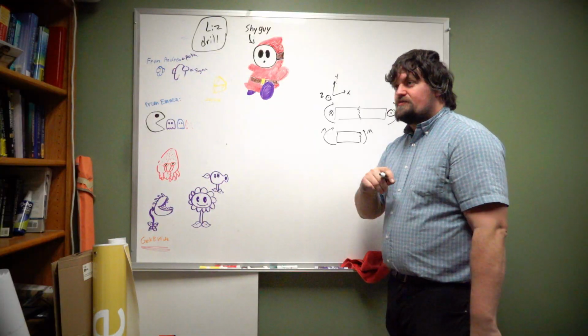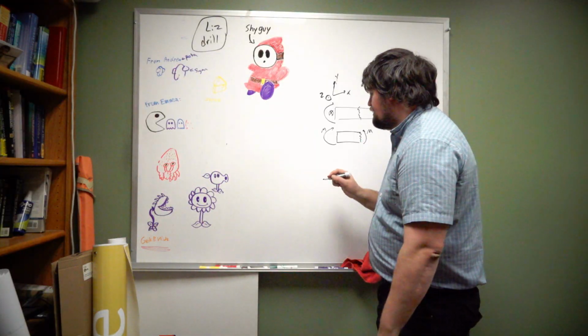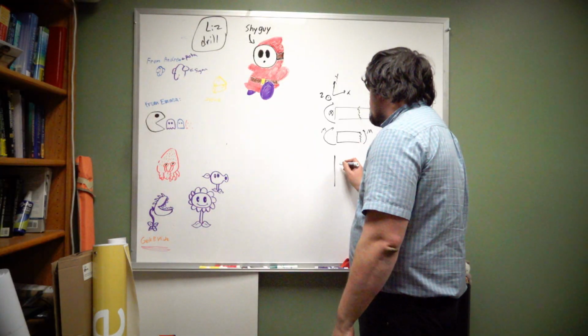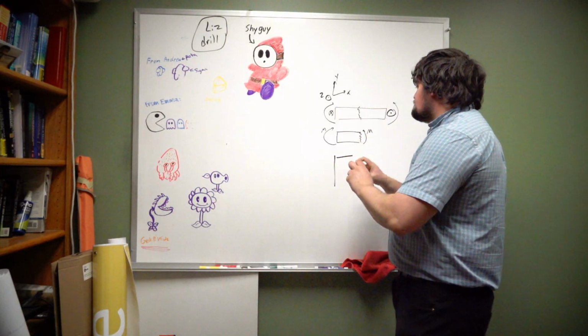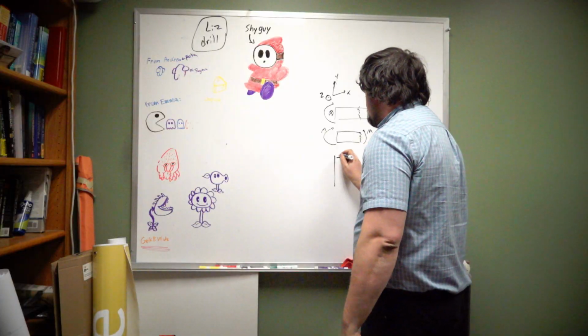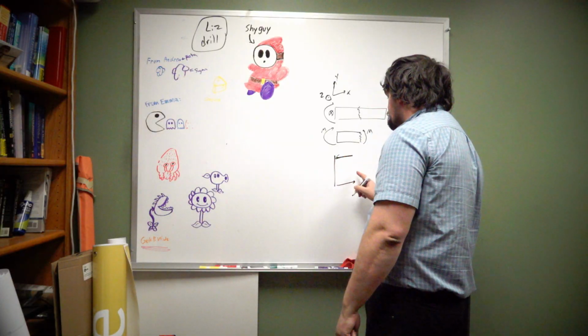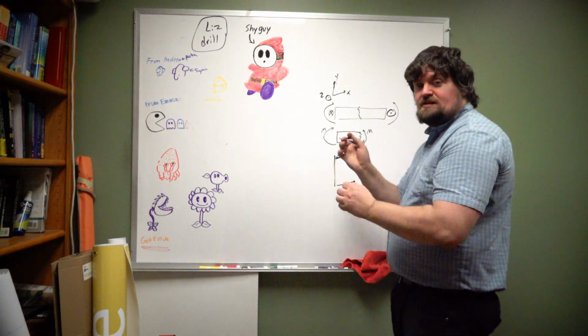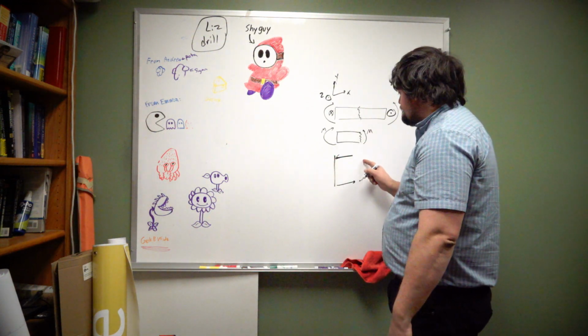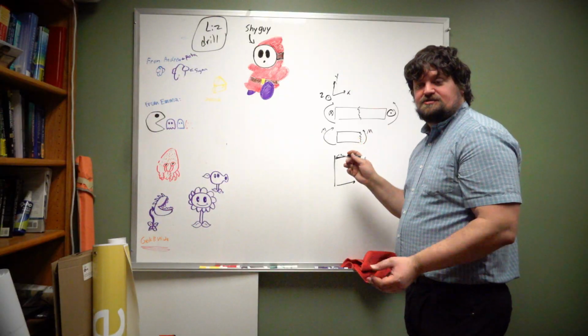Okay. Now, in order for that net moment to be in the Z direction, what we'll find is that there's going to have to be a push and a pull. So here, this one is causing that to be in compression at the top. So there's going to be a push at the top and a pull at the bottom. If that happens, this is a shear loading that is applied here on this cross section.